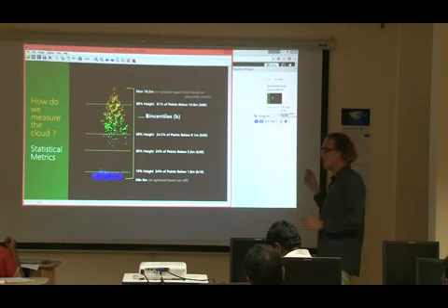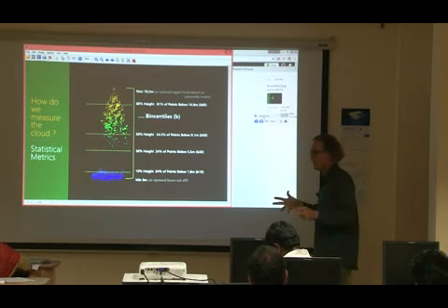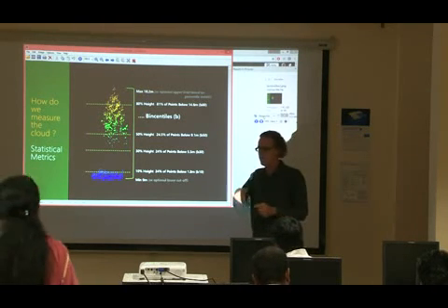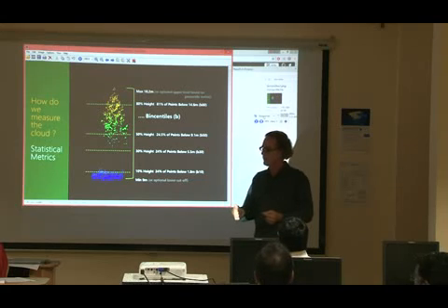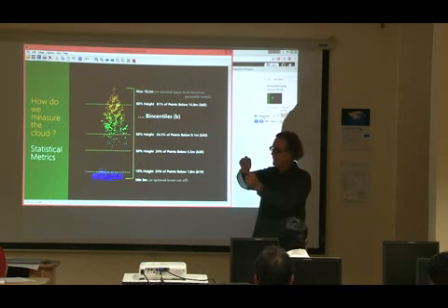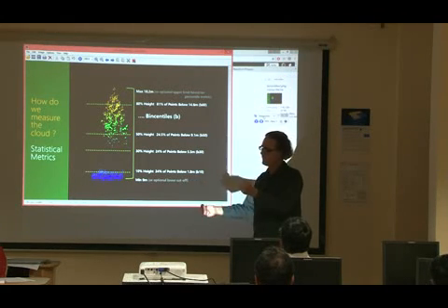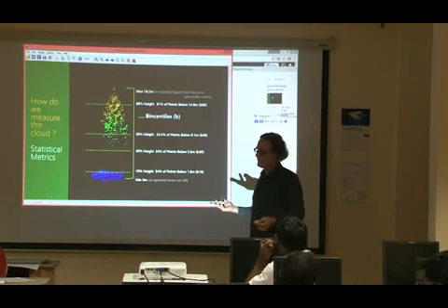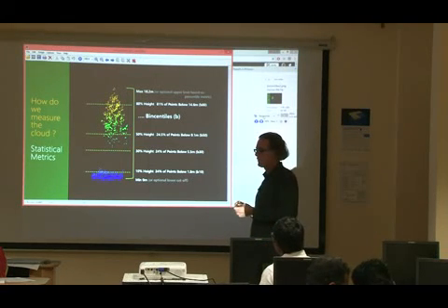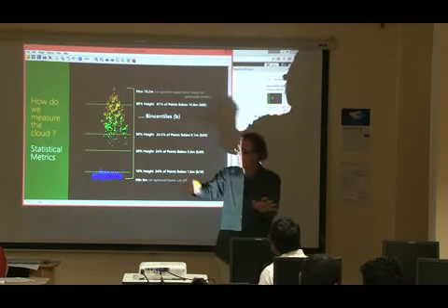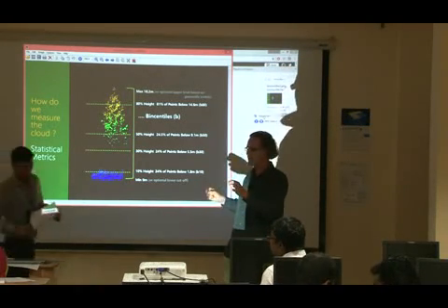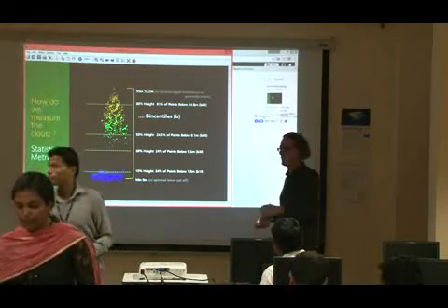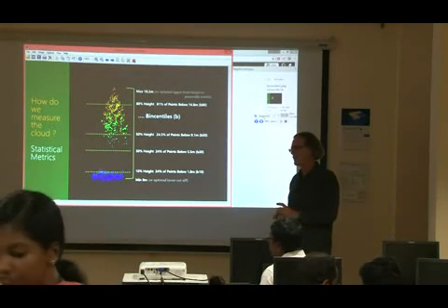As far as I know, it's a satellite with one beam down. That means you're really only getting a line of points. Now, you can process this line of points in various ways with LAStools, but most of the things we do today assume you have an area coverage. I can't do a ground classification based on one line. So you would need different techniques for that.